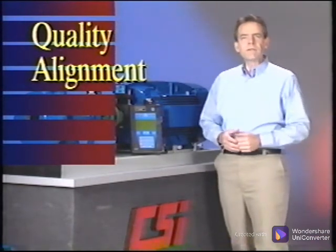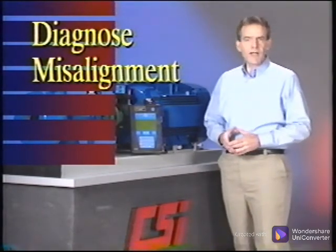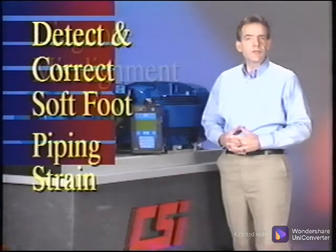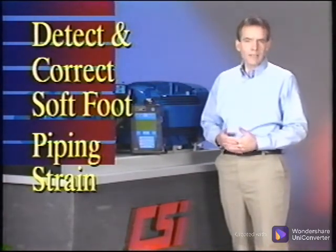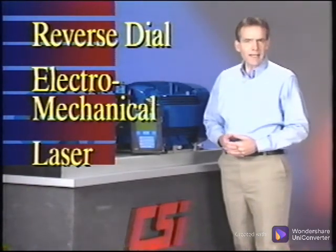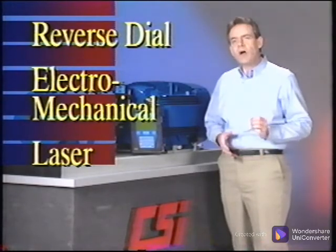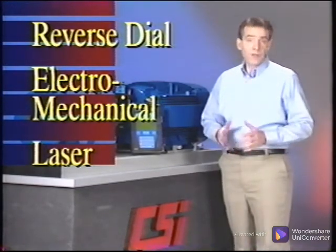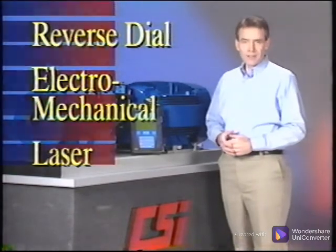We will briefly consider the diagnosis of misalignment using spectral and waveform data, as well as the steps to detect and correct soft foot condition, piping strain, and coupling runout. Precise steps are shown to use reverse dial indicator, electromechanical, and laser systems to achieve a quality alignment and be within tolerances to increase the machine's life and decrease maintenance costs.